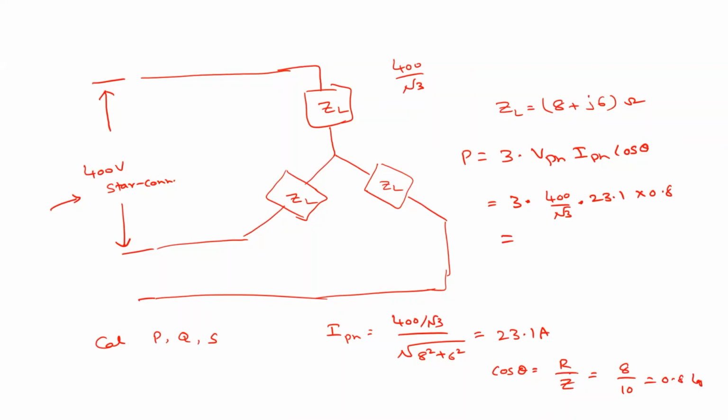So 12.8 kilowatt. Similarly, calculate Q and calculate S. Q is 9.6 kVAR, not kilowatt. What is S? 12.8, 9.6, I think 16. Is it correct? Yes, sir, 16 kVA, right?